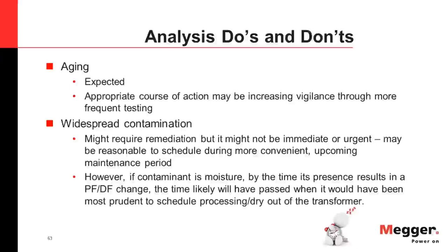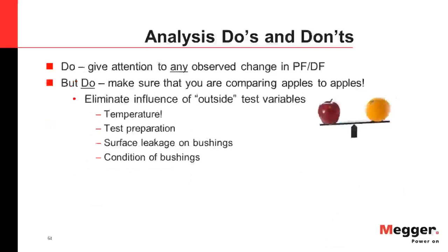When you compare to previous test results, any observed change in power factor really deserves attention. But do make sure that you are comparing apples to apples. And this goes way back to what we mentioned earlier: don't ignore external influences. Because you're paying attention to any observed change, you have to make sure that any possible outside test variables are eliminated from what you're measuring.